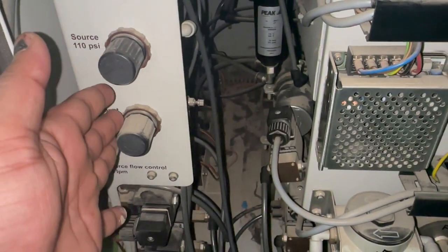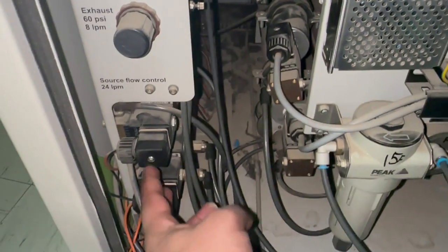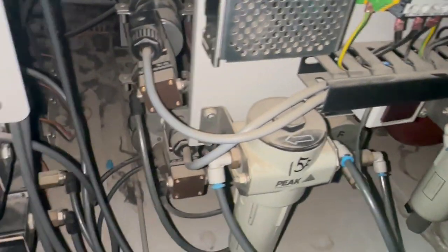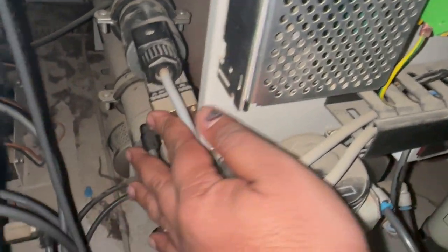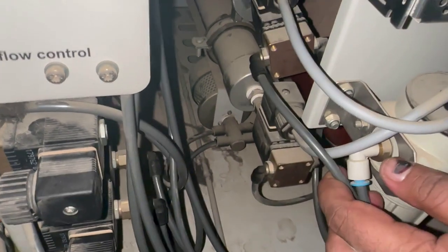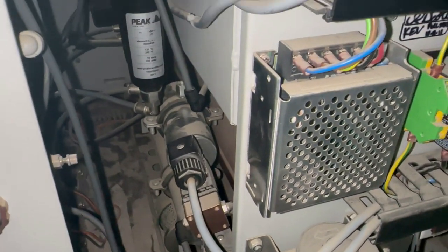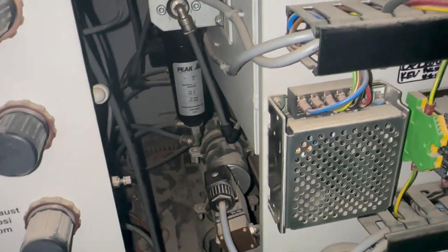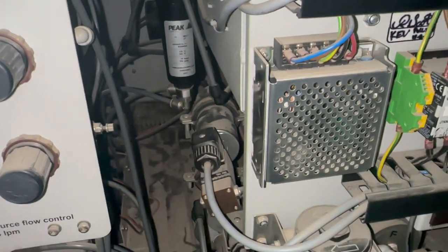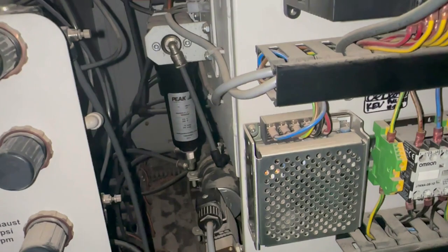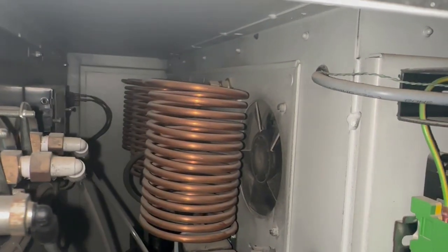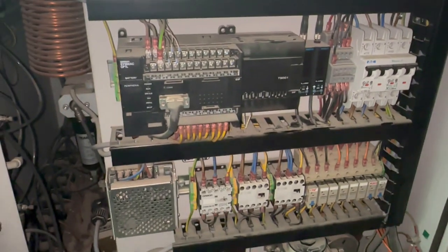So here we have the pressure regulators, and some valves, and the most important thing, here you can see the tank. So there are 2 tanks, one for nitrogen and the second one is for air. And here we have some valves, and the more important thing is the working of its valves. So these valves should work properly, and not only properly, in a specific sequence. So if the sequence is disturbed, this system is not gonna work anymore. Here we have the cooling coils with the fan, and we will troubleshoot all those things. So let's proceed.